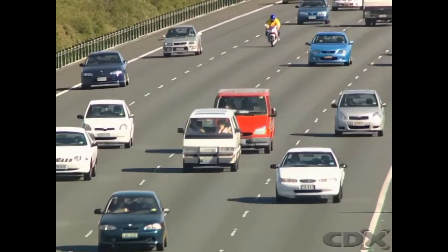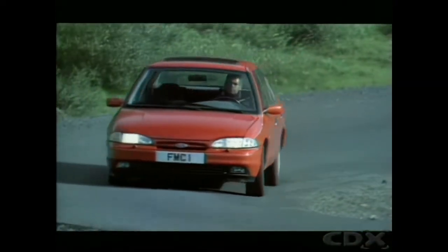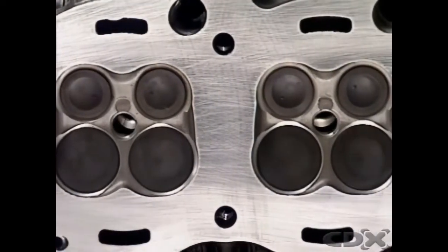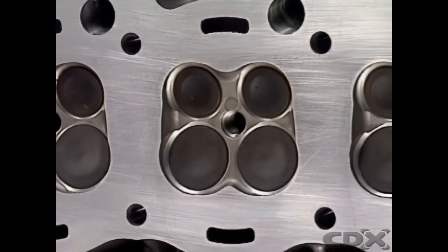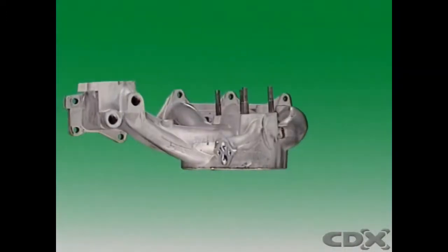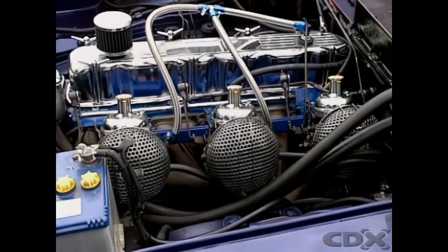On all carburetted systems, the intake system can be crucial in increasing engine output. This can be done by increasing volumetric efficiency, that is, by increasing the amount of air that enters the cylinders. This can be achieved by using a larger inlet valve or multiple valves to admit more charge into the combustion chamber, by using large free-flowing intake manifolds, or by using extra carburetors.